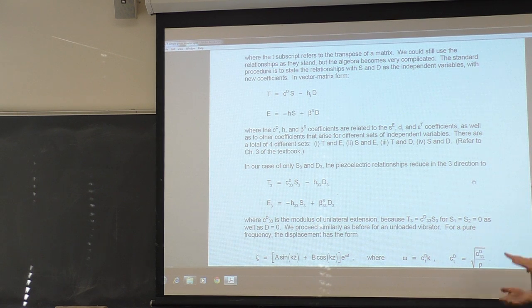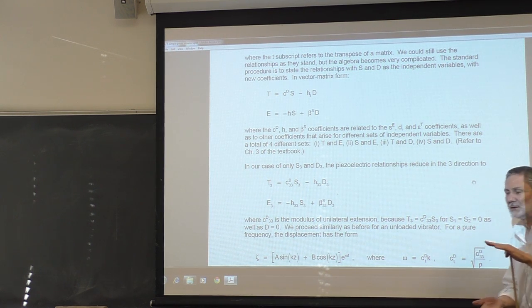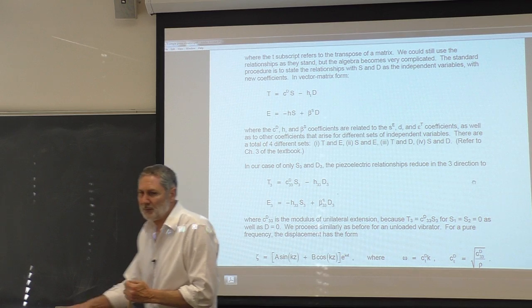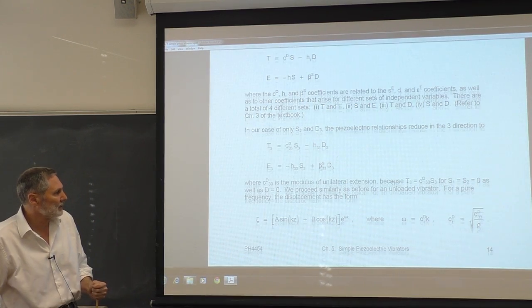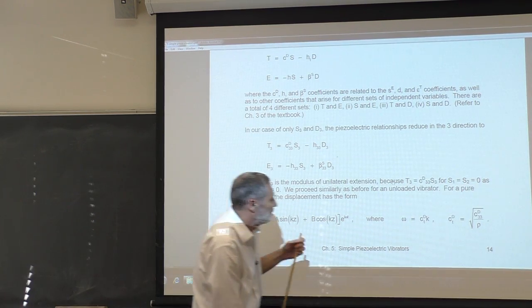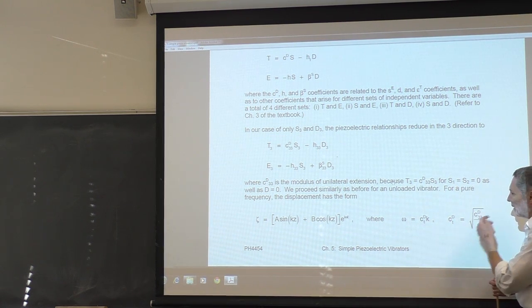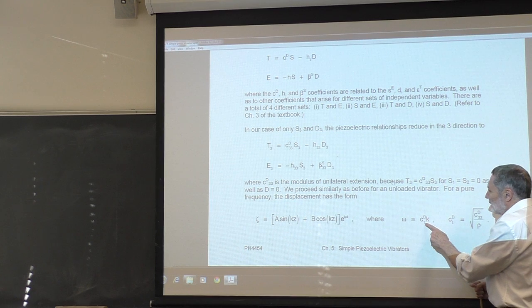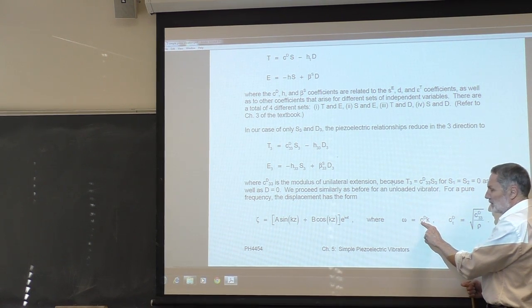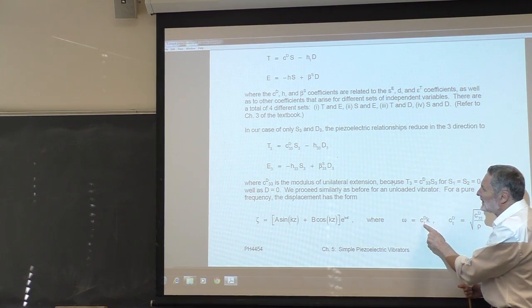So the wave speed is going to be what? The longitudinal wave speed. It's going to be the wave speed not for Young's modulus, but for the unilateral modulus. Brian denotes this, and it gets a little confusing here. This is not a stiffness. This is a compliance.